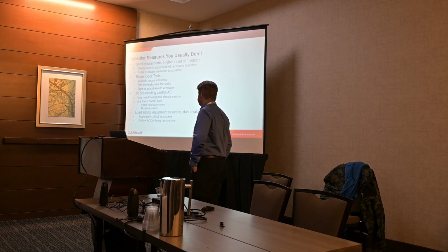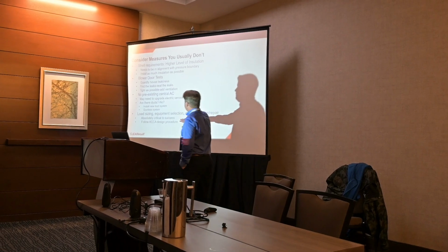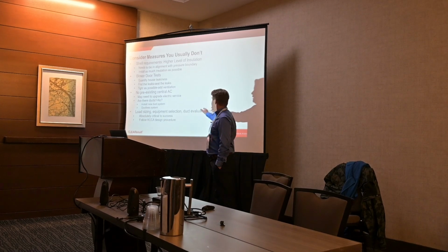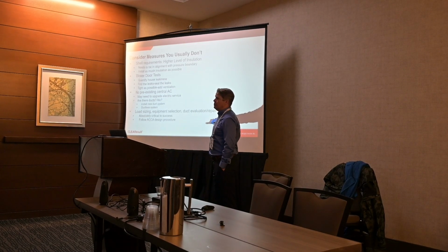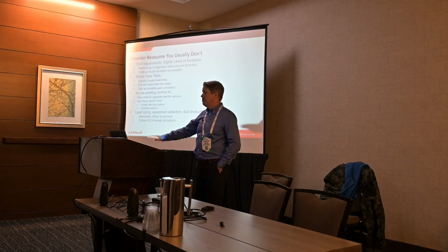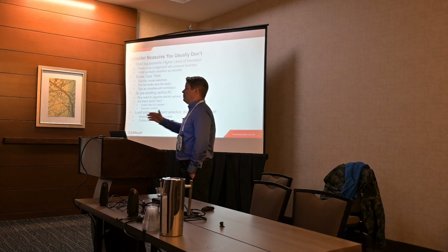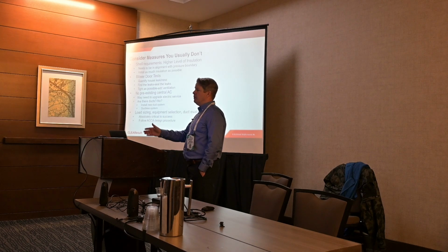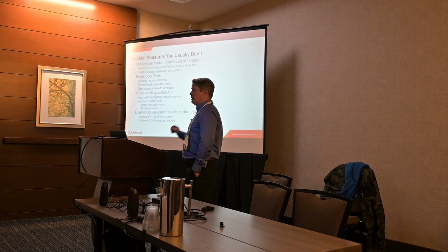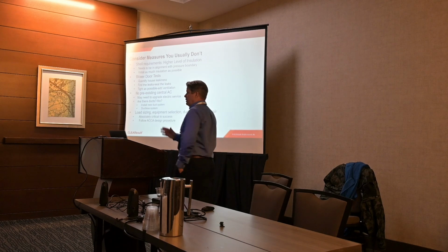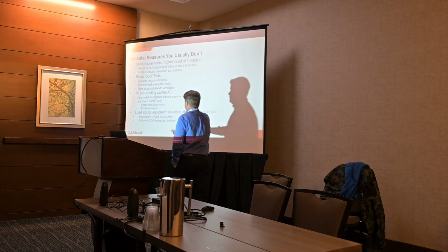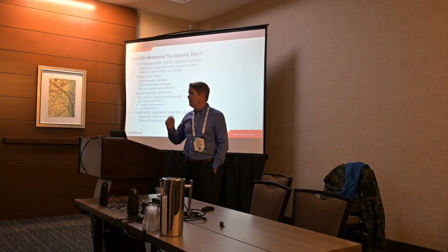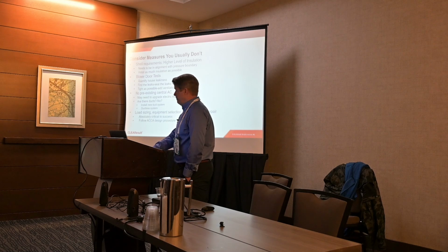Yeah. But what he's saying also comes back again to load sizing, right? And correctly sizing the distribution system. Whether it's a duct system or a baseboard system, the temperature of the water is going to determine how many feet of baseboard it needs to condition that room. And you need to calculate that correctly if you're going to do air to water. So it doesn't matter whether you do baseboard or ducts, it has to be sized correctly, and the distribution system also following the ACA process. Otherwise, we're not going to be successful.